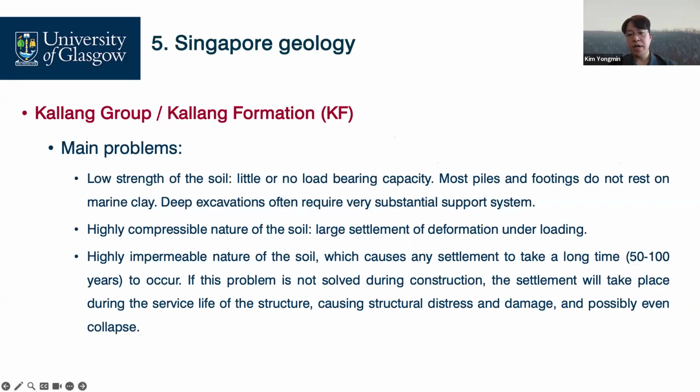And the soft marine clay is highly compressible, so it may cause large settlements. The pretty big problem is that the soft marine clay is highly impermeable.